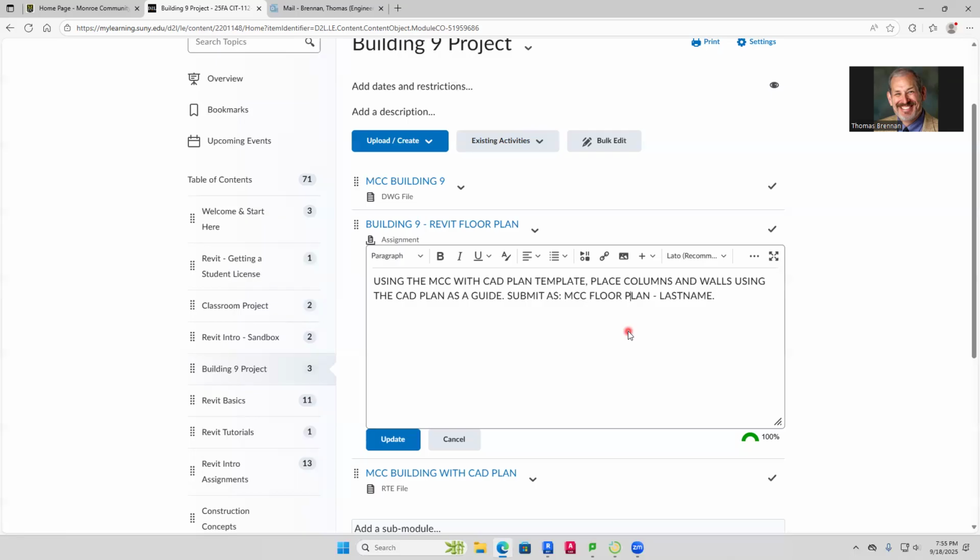Yeah, the White House is pretty. The cantilever sticks out like crazy. And the thing is, there are tables that go with that. I was going to put a cantilever on my deck, and I think for a deck you make cantilevers 2 feet over. That's about as far as you can go with a 2 by 10, and if you have 2 by 12, you go further.